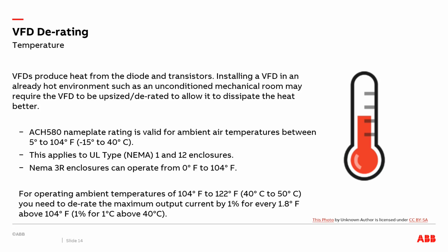So now let's talk about temperature. I mentioned earlier that VFDs produce heat from the input diodes and the output transistors, or the IGBTs. If we're going to install a VFD in an already hot environment, such as an unconditioned mechanical room, the drive may require upsizing or derating to allow it to dissipate the heat better.